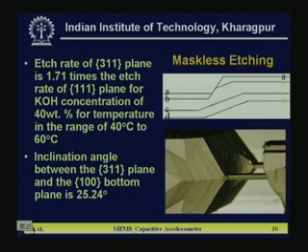So, how to get this kind of structure is again one important issue which you have to practice, and we are doing so in our laboratory to get the flexure at the center of the cross section. Earlier in the piezoresistance case, this kind of flexure does not come into the picture at the top surface, because there we diffuse piezoresistances on the surface of the single crystal silicon. So you cannot make the flexure at the middle of the cross section.